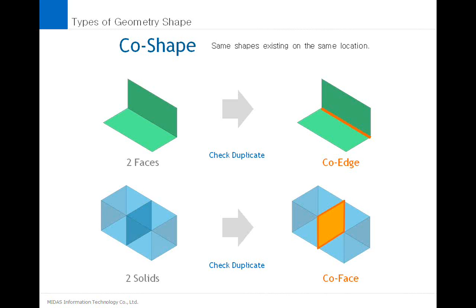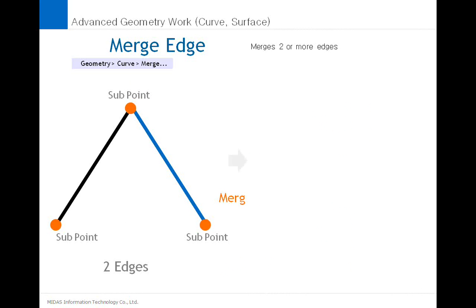It is a very important checkpoint that after solids we always go for a duplicate check, so that we can see the duplicate faces to account for the sharing of face between two solids. And if there is a duplicate, that means there is connectivity, which means we are not going to have any problem with the nodal connectivities in our meshing.